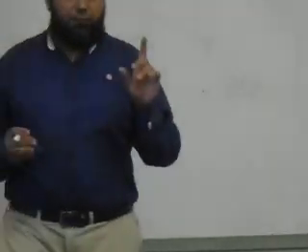We are replacing this, ladies. Look at me. I'll draw it in a different color. I replace this with another easier system because I'm not interested in the vertical members for the time being. When we talk about frames, we will do these vertical members. But we're not interested in them now. We are looking for the bending moment diagram here.